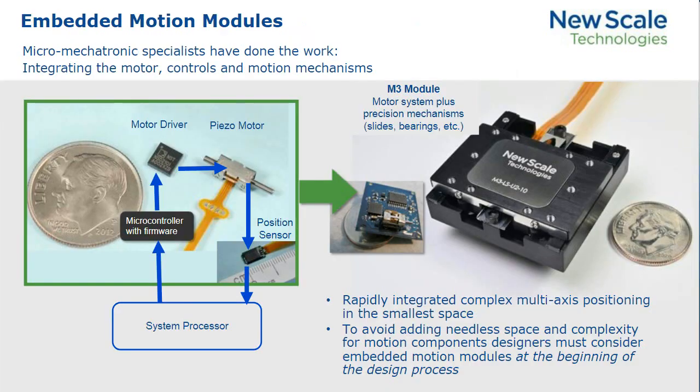Most of the presentation today has talked about electromagnetic motors, coils, magnets, iron, and all the things associated with them to create forces. Most of our products work with ultrasonic piezoelectric motors, and these are motors that work on vibrations. We control vibrations at a frequency that you can't hear or see, but they are used to create continuous motion over many millimeters. We have several types of motors we use. We've created a patented squiggle motor and a UTAF motor, all based on the idea of motion generated from ultrasonic vibrations.